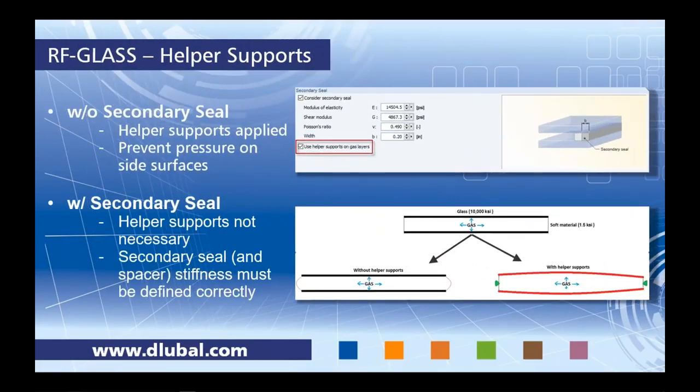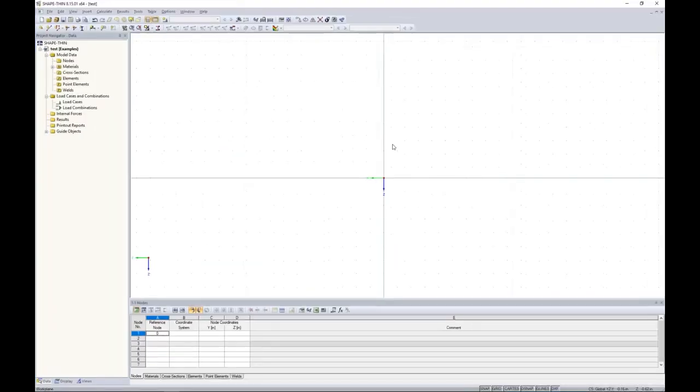Okay, so we are finally ready to jump into our first example. It's quite common with glass design that we want to integrate it with our own custom extruded sections. These aren't sections that you would find within the AISC or the ADM, but rather there's some type of unique cross-section. Well, within RFEM, you most likely won't have access to quickly define this cross-section without having to manually calculate all the cross-section properties. So we've created a program called ShapeThin.